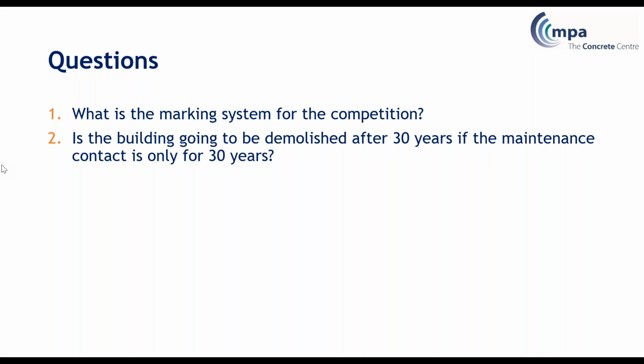Yes. So the lifespan of the concrete frame building: in terms of your specification of concrete, you will need to look at BS 8500, which is a specification of concrete, and in tables A4 and A5, A4 is for 50 years, A5 is for 100 years. You will be looking at A4 because you're looking for 50 years. The concrete will last for longer than 50 years, by the way.